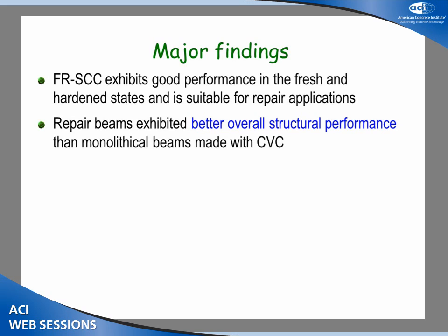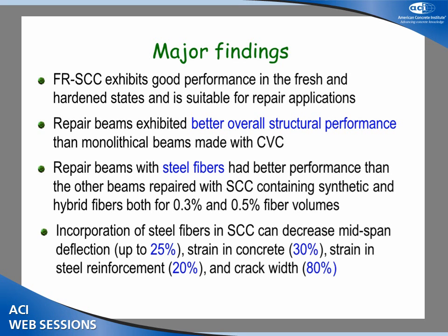The repair beams exhibited better overall structural performance than the monolithically cast beams, which was a surprise to us. You would think that the monolithically cast would be better, but even the repair, given the excellent characteristics of the concrete, gave us equal or even better performance. The steel fibers gave us the best overall performance. This is not a big surprise.